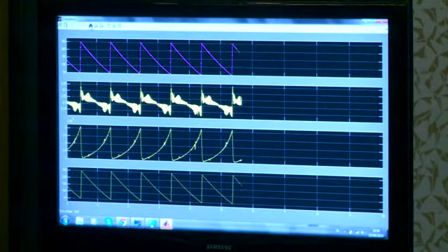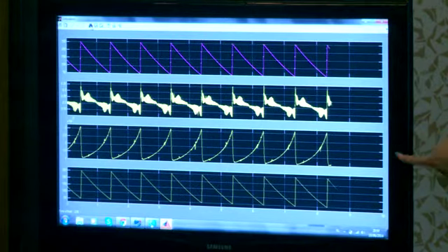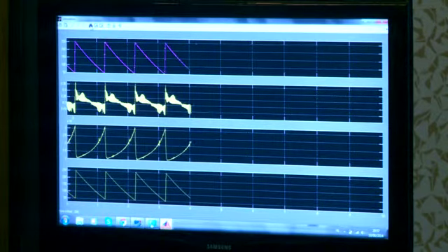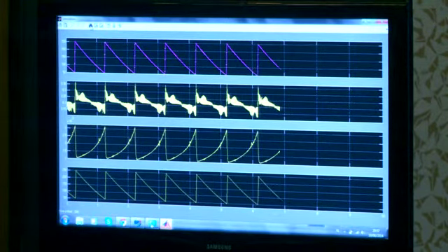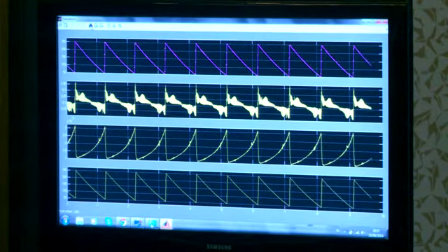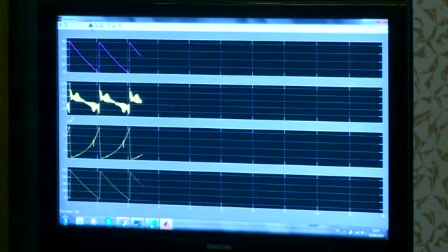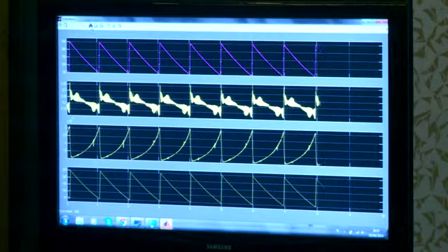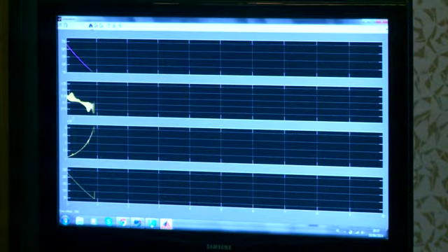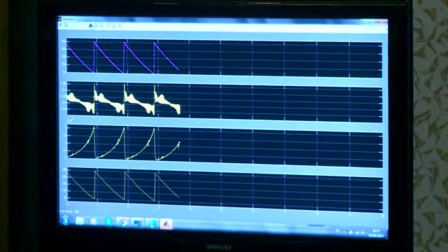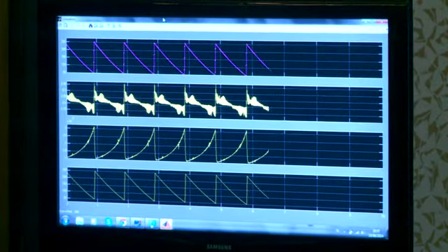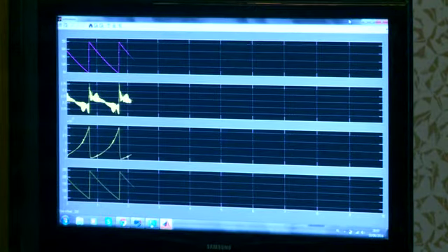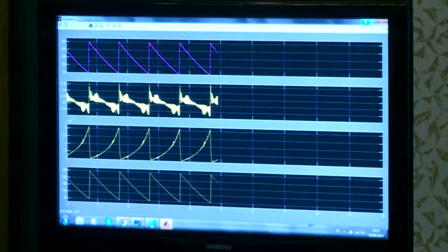This curve here is the conductance, the inverse of the resistance of the light bulb. You can clearly see as the light bulb goes on, the conductance drops, which means the lamp heats up, the resistance goes up, so the conductance goes down. As the light bulb slowly discharges, the conductance goes up again, which means the resistance is dropping again. So you can identify the time varying characteristic of your light bulb, and that is information you could use through your observer in your system simulation.